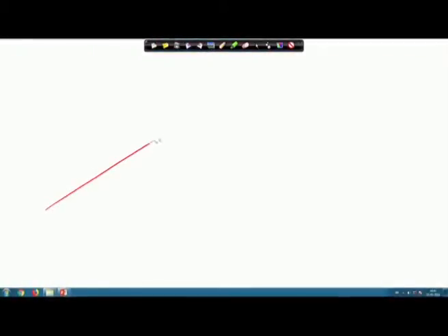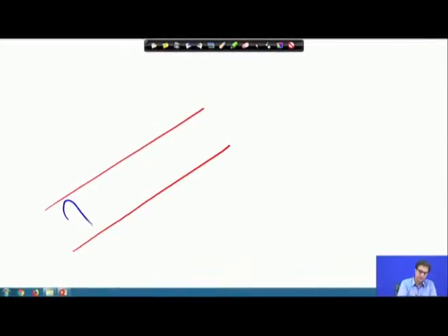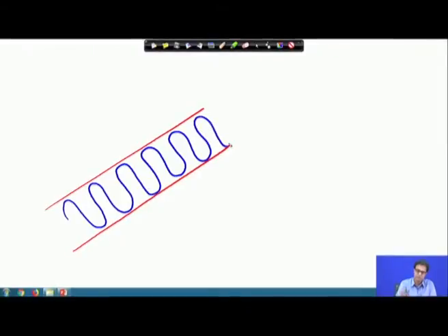So far, in the case of plate fin type exchanger, we have talked about the separating plates, and in between the plates we have some fins connected. Between the two separating layers we have fins joined, and we have talked about the bridging between the separating plate and the fin, and we have ensured that there is a good thermal contact between the plate and the fin.